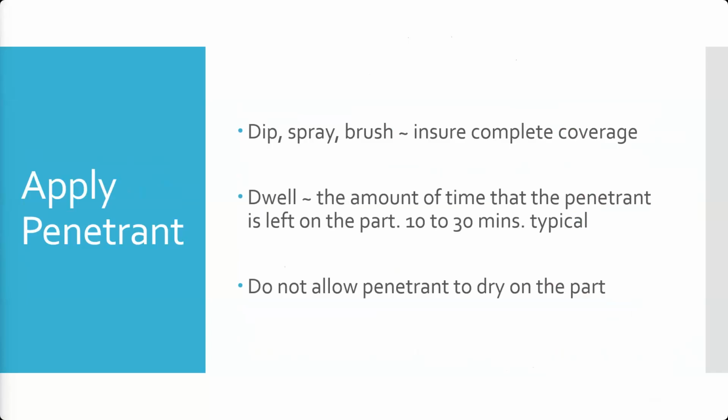The dwell time is the amount of time we allow after we've applied our penetrant. We have to allow it to get into all those cracks, crevices, deformities. Typically 10 to 30 minutes. The procedure you're following is going to tell you how long that needs to be. It's going to be provided by the manufacturer or other engineering authorized representative for whatever component you're working on. Okay.